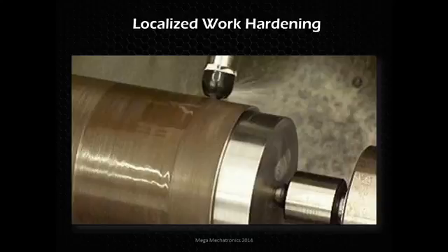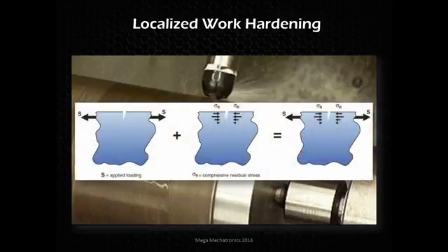And then touching on compressive stresses, why those are important. If we look at, on the very left, a material, let's say it has a little crack in there, but if there are compressive stresses, everything's trying to push things together. Those compressive stresses are pushing that crack back together. So when you apply that load to split that crack open, there's actually compressive stresses countering that, and that's what gives it fatigue strength and things like that when you shot peen a part or roller burnish it.